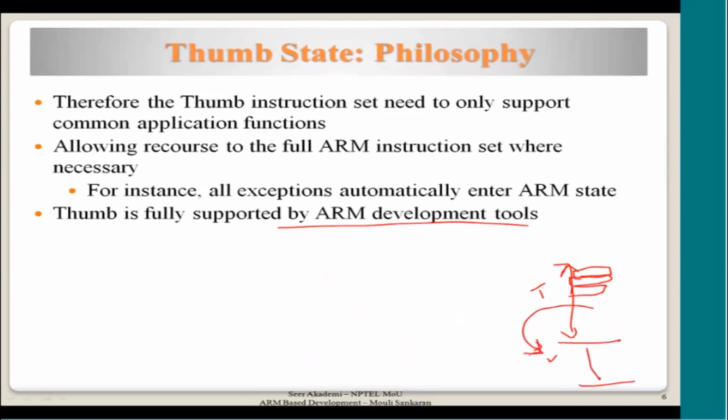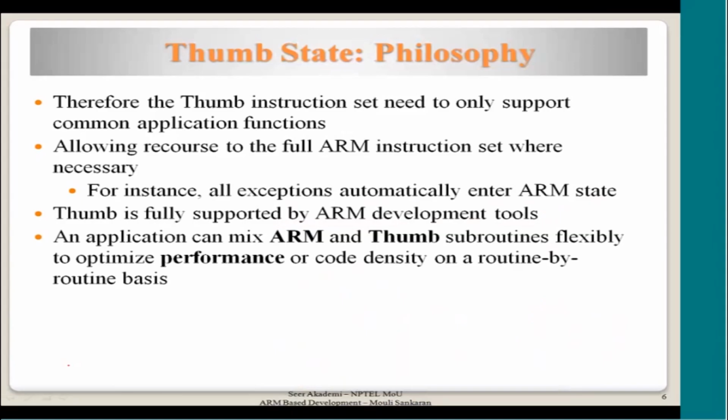You have to make sure that when you come into this ARM code, the mode is modified. Okay, and then it starts executing the ARM code. So the development tools, all of them support both the modes. An application can mix both ARM and thumb mode subroutines together.